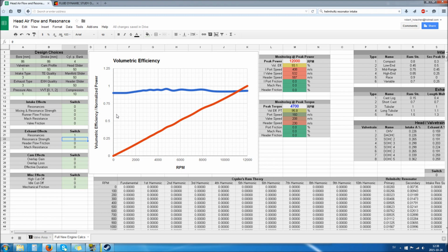But the big difference to the intake side is that we have stronger effects from the primary pipe firing, sending down a pulse, and where the exhaust is collected, where the primary pipes are collecting, that pulse will be reflected back, but not only into the primary pipe, but also into the others gathering there. So you can have more different frequencies in this whole array of primary pipes being collected.